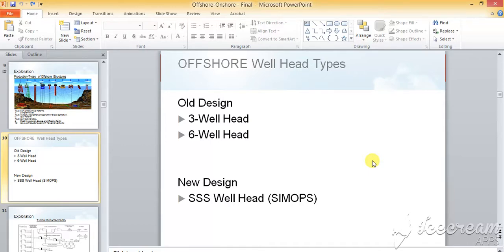The observation well is used just to collect the data of the reservoir, how much material or product the reservoir has been left with. Secondly, they'll note down the specific gravities, densities and other things, the H2S content and the CO2 content inside that reservoir, and how it is changing with the